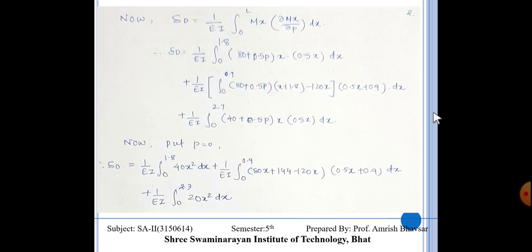Delta D is equal to 1 upon EI integration 0 to 1.8, (80 plus 0.5 P) into X into 0.5x dx, plus 1 upon EI integration 0 to 0.9, (80 plus 0.5 P)(x plus 1.8) minus 120x into 0.5(x plus 0.9) dx, plus 1 upon EI integration 0 to 2.7, (40 plus 0.5 P) into x into 0.5x dx. Now we put the value of P as 0.